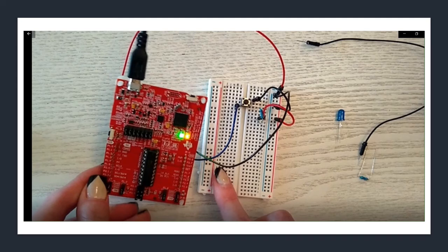This helps with troubleshooting. The reason I do this is to make sure that nothing is wrong with my code. Because if I plugged this push button into another pin and something wouldn't work, I wouldn't know if I had coded something wrong or if something was wrong with my circuit. So we have an advantage here because this is so simple. We already have a push button and LED on our board. So I can run through my code first and make sure that works using the board components. And then by connecting the external components to the same pins, I can verify that my circuit is built correctly.